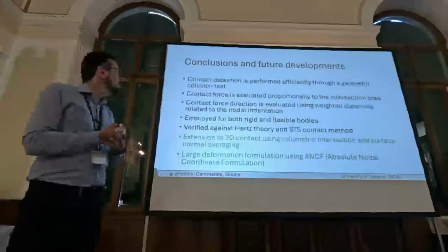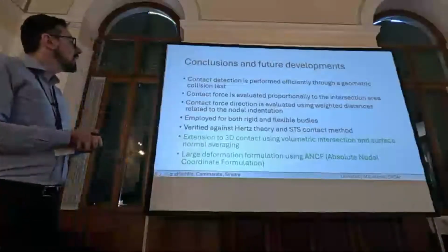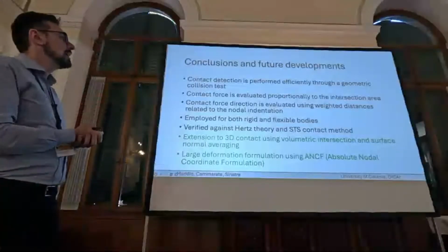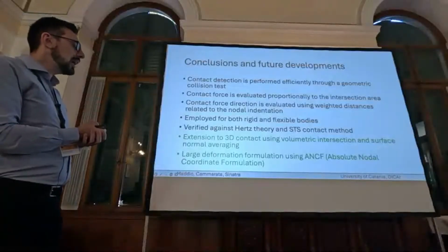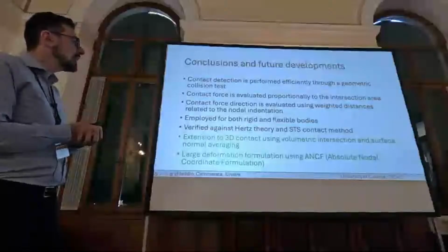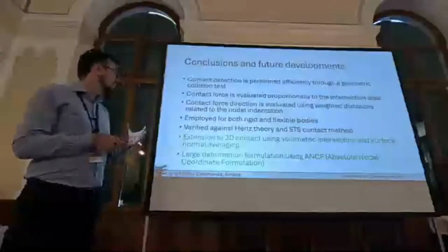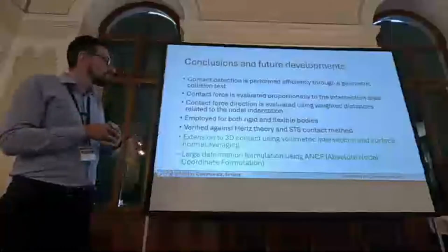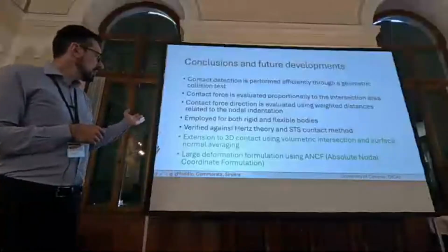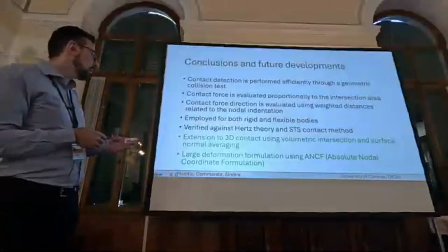So to conclude, we formulated a penalty contact method by using directly the formulation with the intersection area. We evaluated also the nodal contact forces, and we employed both rigid and flexible bodies, and we verified the method against the Hertz theory and the STS contact method.